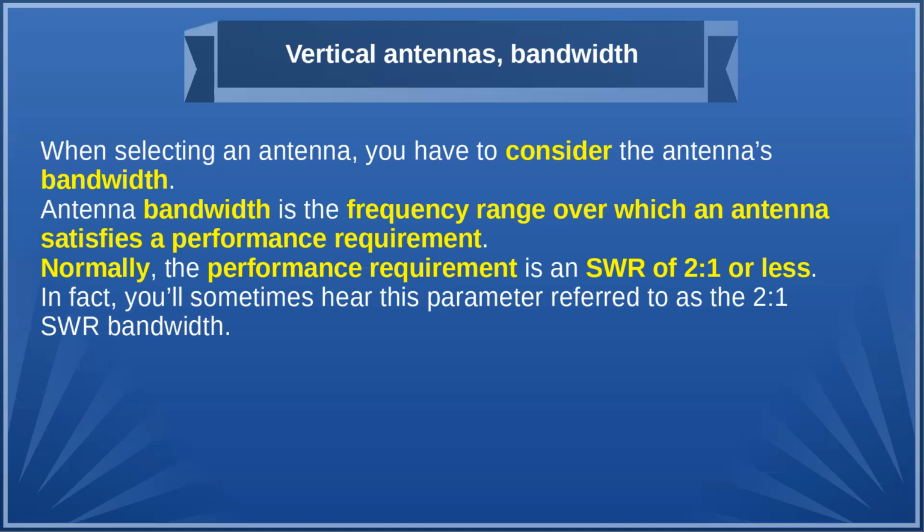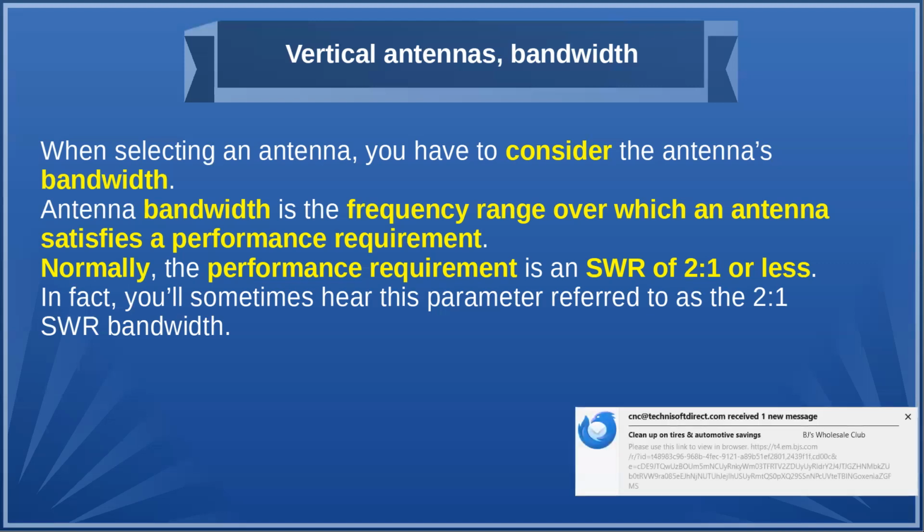If it's 3 to 1 at the antenna, it's still 3 to 1 at the antenna, whatever you do. You've got a standing wave coming back down the transmission line to your so-called tuner. The antenna tuner is really not tuning the antenna, it's keeping your transmitter happy. It's a matching unit.